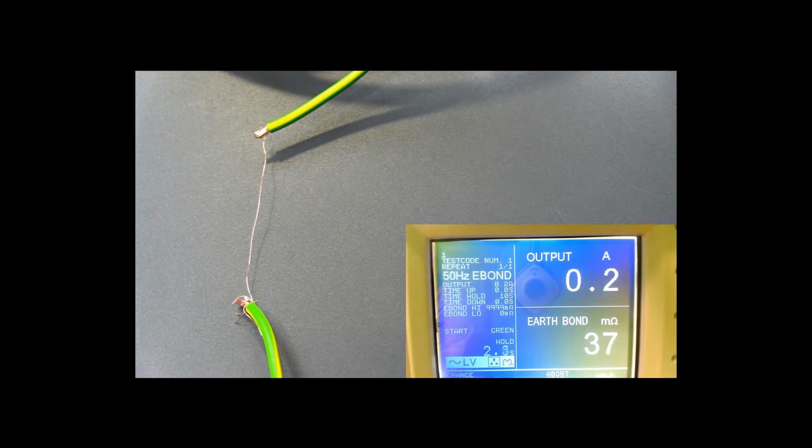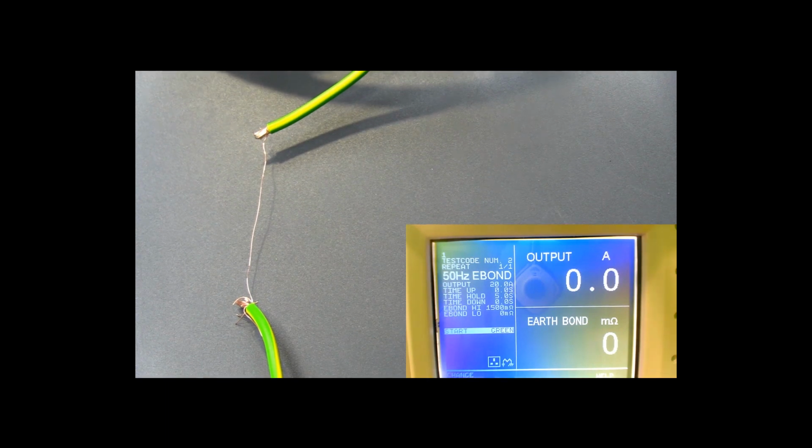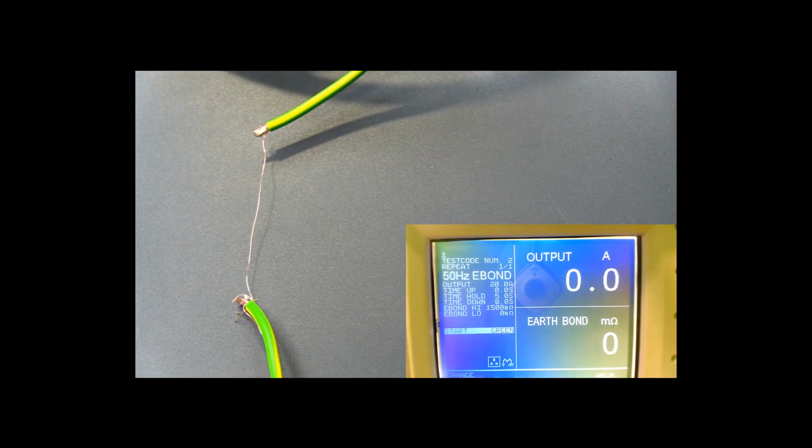So the test has started. You can see there's no effect on the cable, it's carrying the current without issues. We'll run it for 10 seconds and everything's good, the test has passed. There's been no highlight of the poor condition of the cable. Now, although on this particular instance we're getting a reading of the resistance, if we use a more traditional light indicator or even an audible indicator, all we would know is that we have current. We wouldn't know about this potential condition.